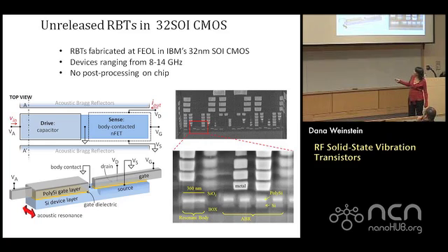What we also saw was actually some wonderful metal Bragg reflectors, or phononic crystals, which got formed. These were not intentional. These are formed using the CMP fill step, which the foundry puts in for you, which we only found out after we got the chips back. That was the first process. There's ways to get rid of it, or to manipulate it to do what you want.